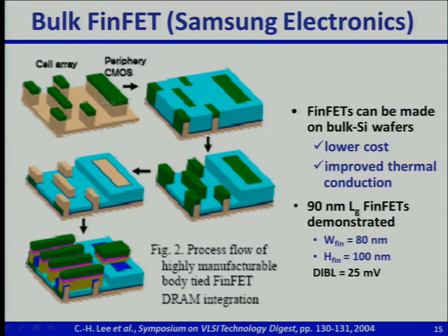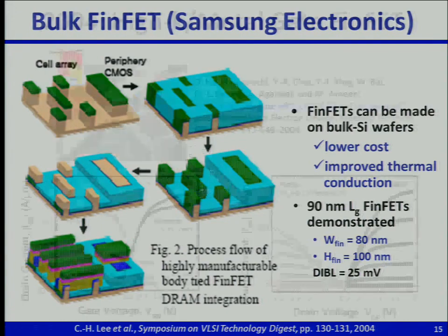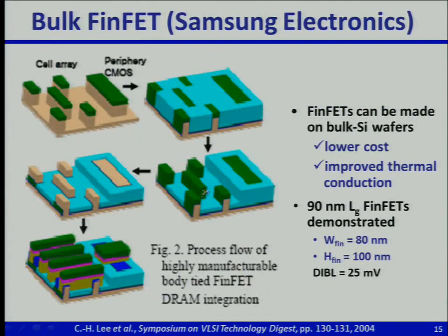But to make FinFETs, all you have to do, well, it's not trivial, is to define your silicon transistor regions to be very narrow. Okay, so if you define your silicon transistor regions to be very narrow, and then you have one extra step with a mask. So you have a mask to only allow etching of the STI, the shallow trench isolation oxide. Here, where you want to form FinFETs, you can have a masked etch or recess etch of the silicon dioxide shallow trench isolation to expose the sidewalls of the fins.